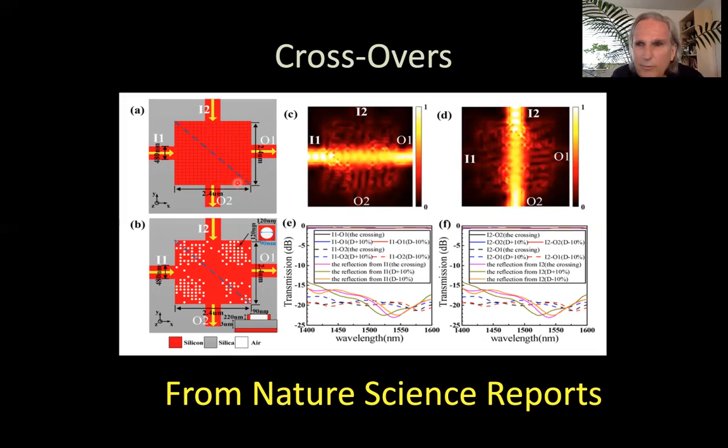People have to optimize them, and it has to be done by hand and by trial and error. Again, with these, you're getting the losses down at design wavelengths well below minus 20 dB, so below 1% loss. So if you could start doing these with 64 channels in and 64 channels out in tiny distances, we could start talking about really minimizing layout.